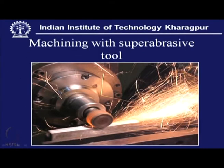So, this is one example of super abrasive machining engaging a super abrasive tool, and this is just a steel core on which one layer of super abrasive grits are anchored or bonded, and that works at a very high speed, generating huge amount of spark, but at the same time removing large volume of material which is comparable with that of machining, but at the same time the surface quality which it is going to produce is as good as that of grinding.